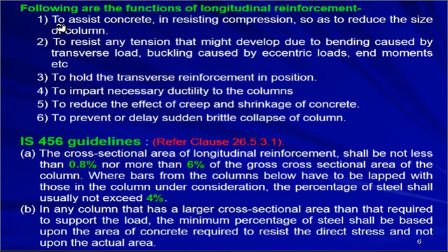What are the functions of longitudinal reinforcement? One by one we will see. First, to assist concrete in resisting compression so as to reduce the size of the column. The load carrying capacity of steel is quite high compared to concrete, and obviously if you add some percentage of steel, it reduces the size of the column. Second, to resist any tension that might develop due to bending caused by transverse load or buckling caused by eccentric loads and end moments. Third, to hold the transverse reinforcement in position. Fourth, to impart necessary ductility to the columns. Fifth, to reduce the effect of creep and shrinkage of the column.